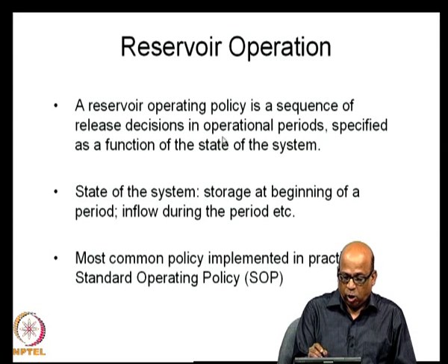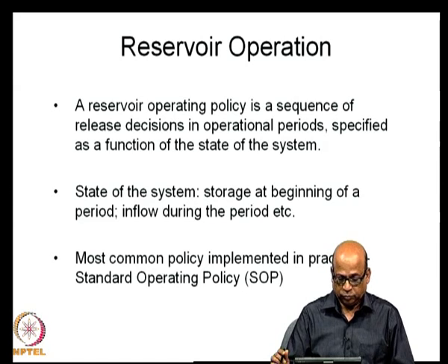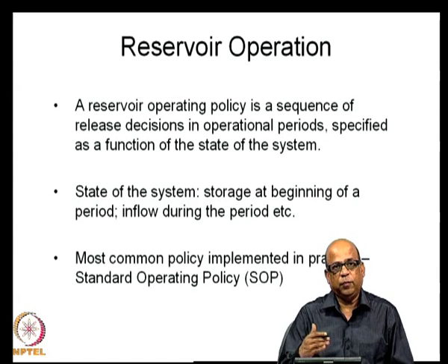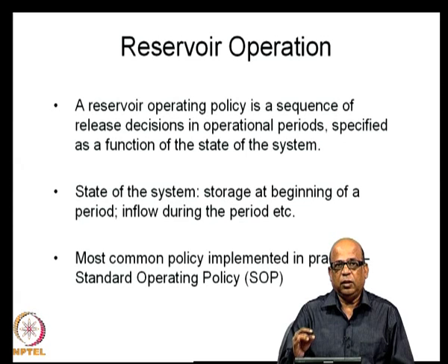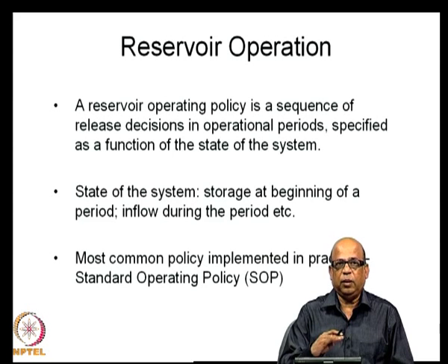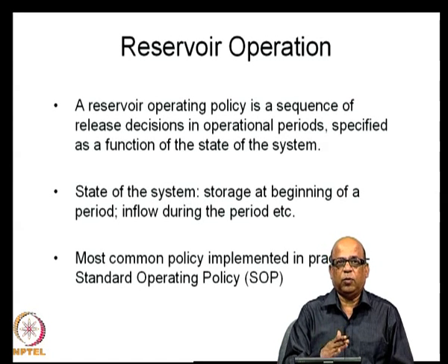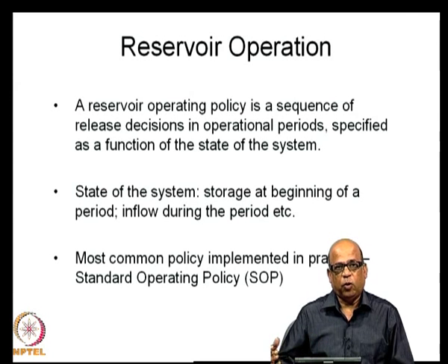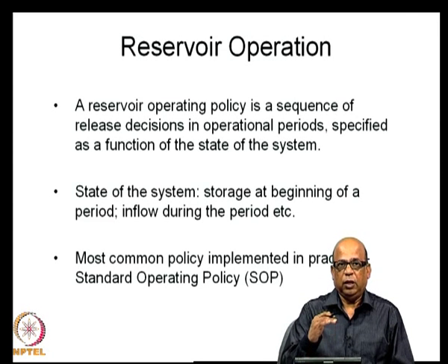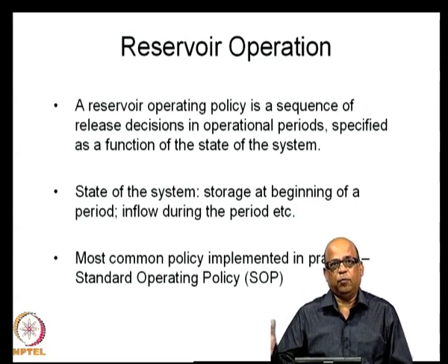So, the operational periods will depend on the specific purpose for which the water resource system is being operated. And as I said, you may want to specify the release sequences as a function of the state of the system, and the state of the system typically can be defined completely by the storage available in the reservoir at the beginning of the time period, or both the storage as well as the inflow, or if you want to include more details, storage, inflow and the soil moisture in the command area, storage, inflow and the rainfall in the command area, and so on.